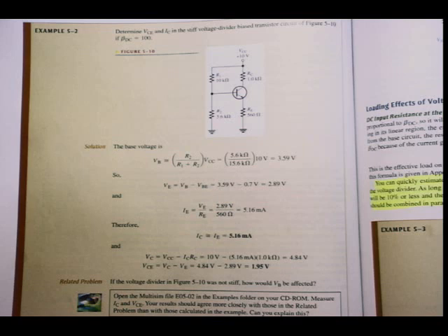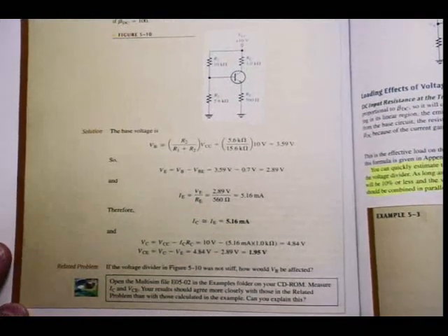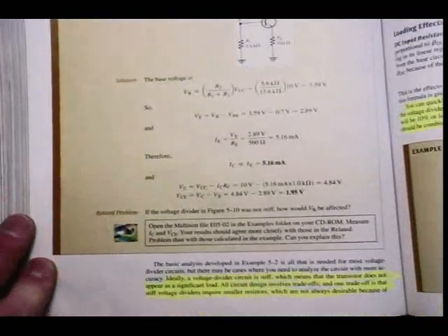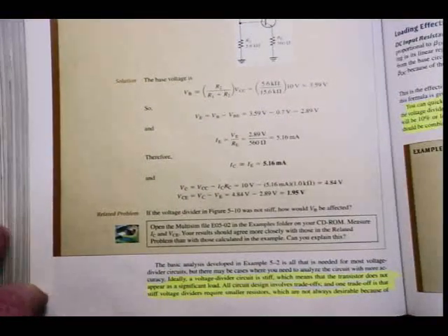That's very important. Remember, if I ask you to calculate VBC, it must be VB minus VC. If I ask you VCB, then it's going to be VC minus VB. Because it's going to affect your polarities. Né? So if you don't keep that in mind, your answers are going to be wrong. But this is important, you can mark it NB at the bottom of this example.